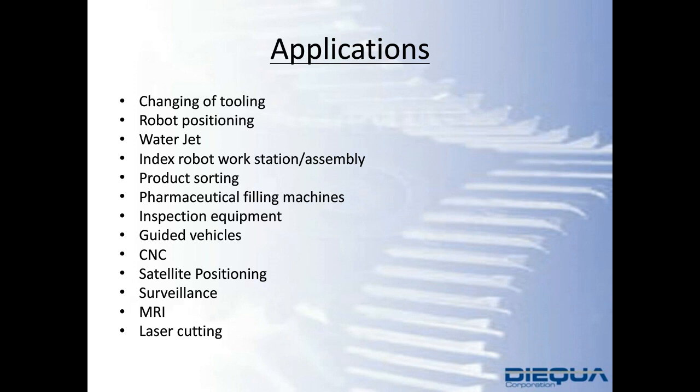When we work with satellite positioning, you have the chatter or the feathering, right, of the wind pulsating onto the face of the reducer. What this is going to cause is micro shocks on the shaft connections, on the bearings, and so this is where having multiple bolts securing the flange to the satellite would help increase rigidity.